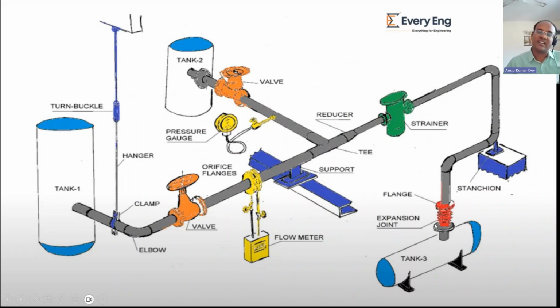So all those displacements and other details we have to provide in a data sheet to the manufacturer so that they can provide exact details as per our requirement, and also check whether the space available for the support installation is proper and the supporting is proper. So all those things we will be studying in our pipe stress analysis programs, and then we mark whatever is our requirement in the isometrics, and we prepare various data sheets also, spring hanger data sheet, expansion joint data sheet, and we give them to manufacturers for procurement purposes. So this is roughly the basic aim of pipe stress analysis.